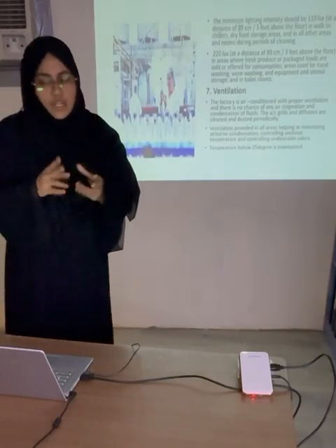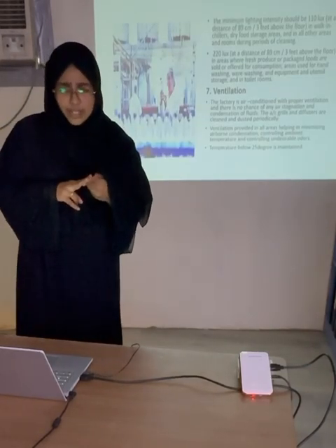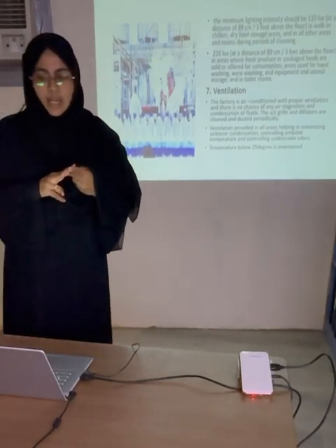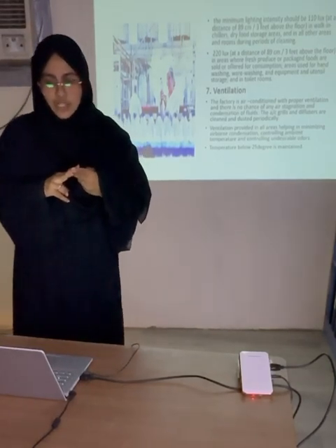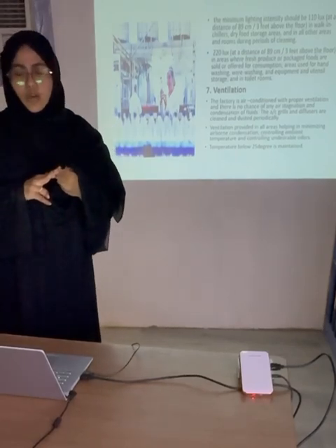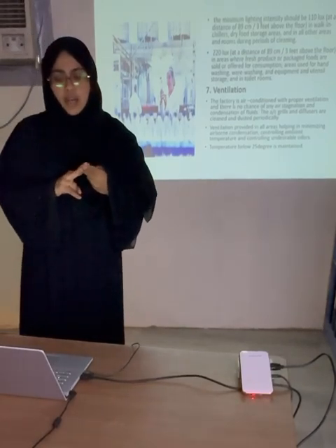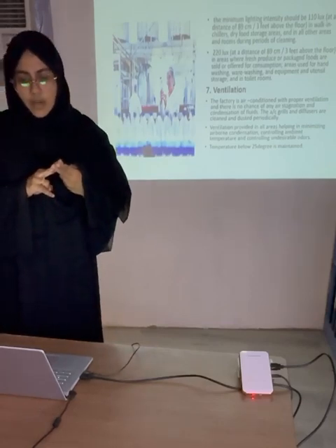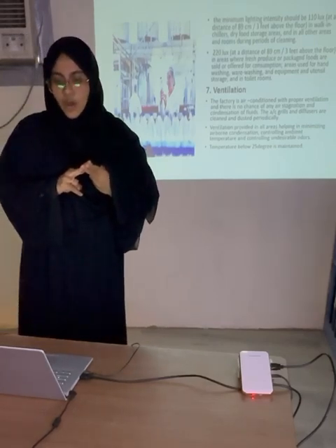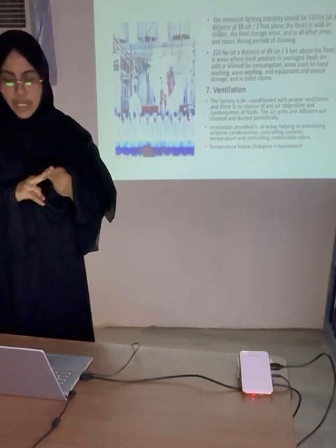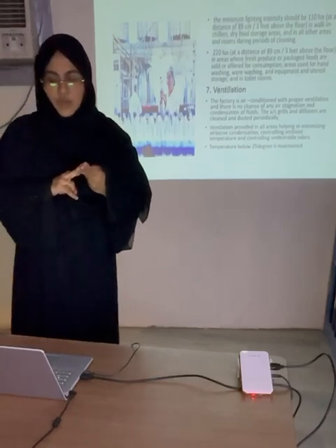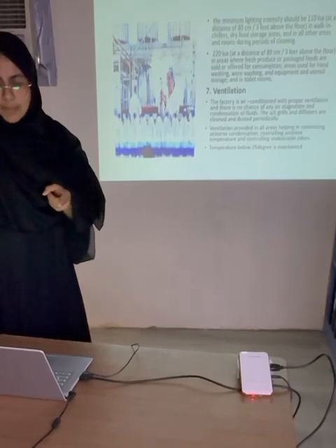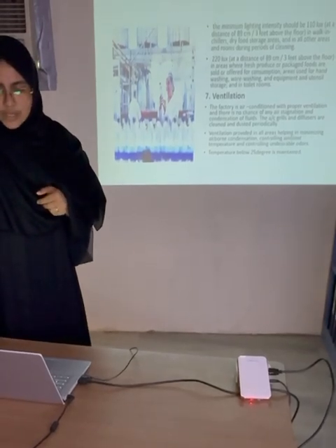There are two lighting levels usually provided in our factory. In certain areas like dry food storage or the chiller, we keep a light intensity of 110 lux, measured about 3 feet above the floor. In areas like the food preparation area, we keep around 220 lux of light. It is also applicable in storage areas.